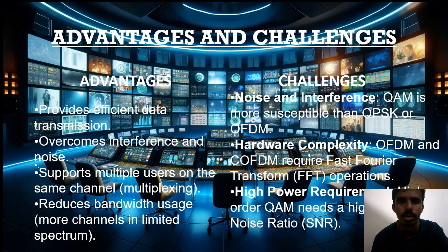So now let's look into the advantages and challenges. Advantages first: provides efficient data transmission, overcomes interference and noise, supports multiple users on the same channel, reduces bandwidth usage, more channels in limited spectrum. Now the challenges. Noise and interference: QAM is more susceptible than QPSK or OFDM.